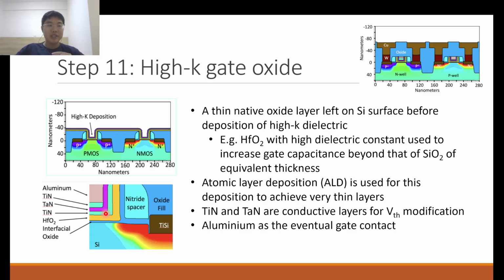And that's very important because some of these layers are easily oxidized. So if I break vacuum, take it out of the vacuum, then put it back in, and I expose it to air in the process, these very thin layers can get oxidized. And when we have things like electrical contacts there, we definitely do not want any oxidation, because that increases the contact resistance, changes the electrical performance of the device and things like that.